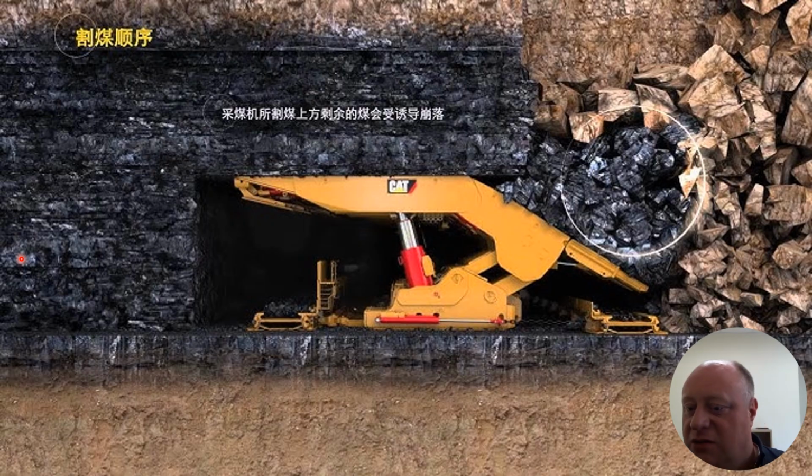And then eventually along came top coal caving, right? Where you basically just take the shield, make it a bit bigger, add this extra flippy gate on the back, right? So you've got an extra piece of shield, a gate that opens, a second AFC, a second armored face conveyor.